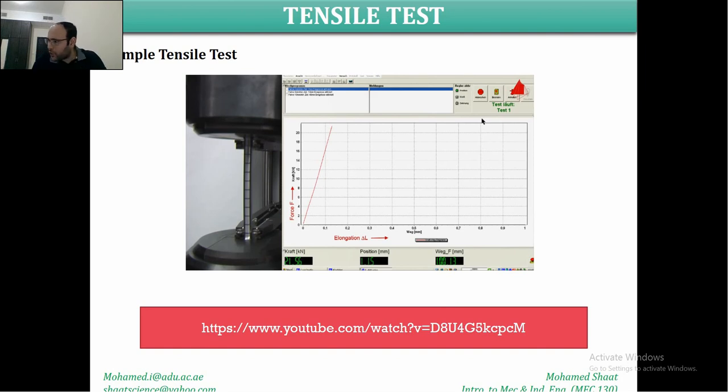If I remove the force, this extra 0.13 millimeter will be eliminated and the material will restore back to its original length, which is 100. When you measure, if I remove the material sample and measure the gauge length, it will be 100. What about the 0.13? It has been restored. Why? Because the material is still in its elasticity region, in its elastic behavior. This is what an elastic behavior of the material means. It means that the material behaves like a spring.